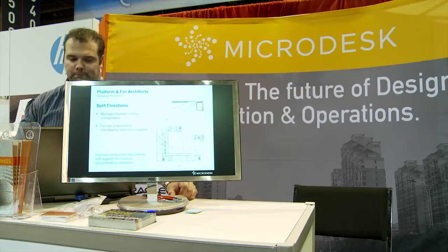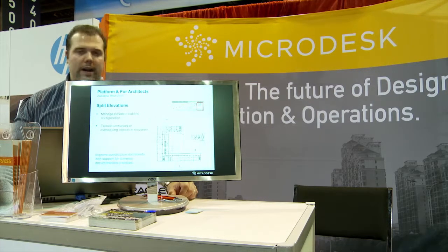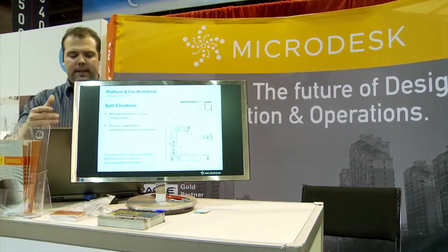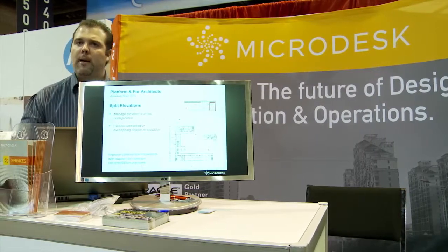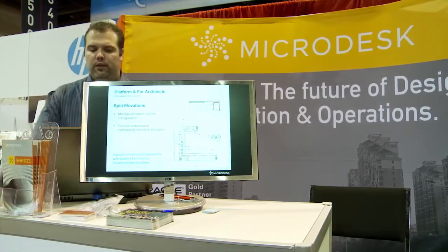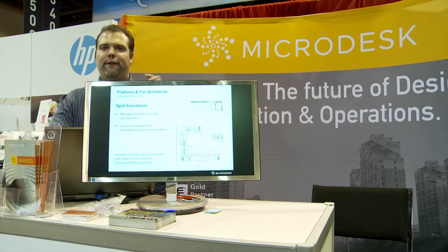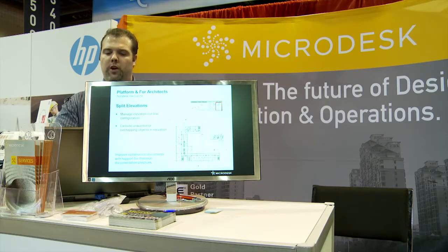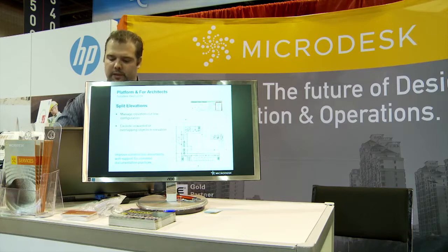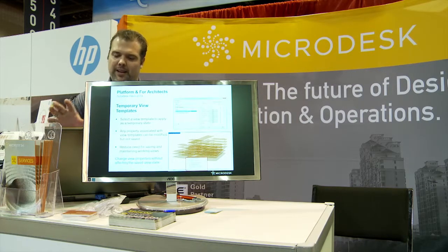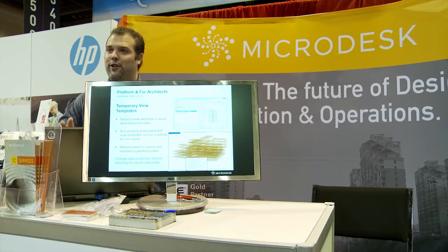So very, very cool. And talking about what I mentioned before, which was related to how you can split and control the view crops, you can now do the same for elevations. Although you have this feature available for sections, you know how many times I saw people faking elevations as sections just so they can do this? So they can create their own workaround, semi-elevation, just using the section tool. Now you can do that with the elevation. Really, really cool. You usually get a standing ovation halfway through this presentation because there are some very cool features.